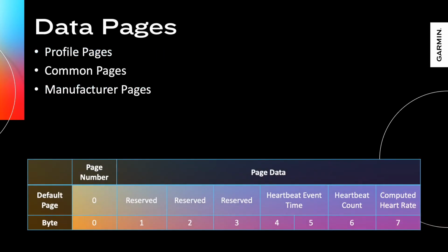8 bytes of application data can be encoded each time a message is transmitted over an ANT channel. ANT+ device profiles specify encodings for this data. In ANT+, the first byte of each data message is always the page number. The encoding for the remaining 7 bytes changes depending on the page number. Together, we get what is referred to in ANT+ as a page.